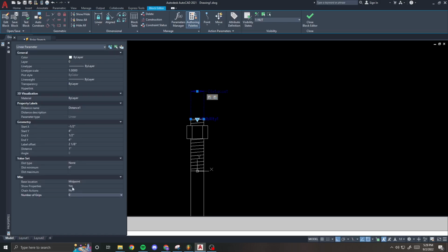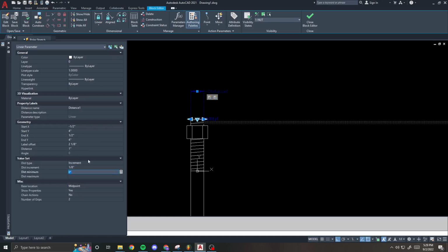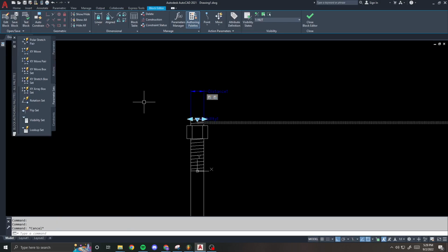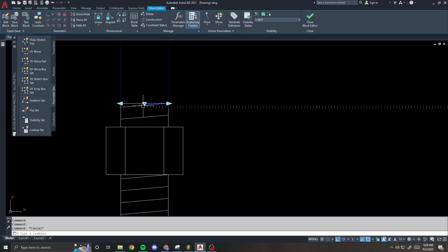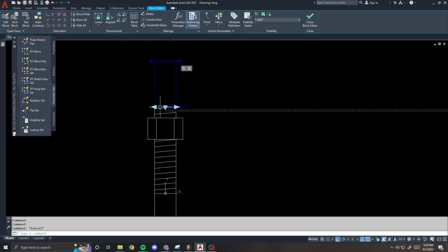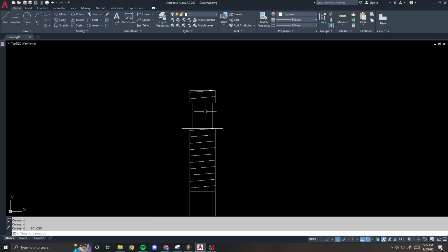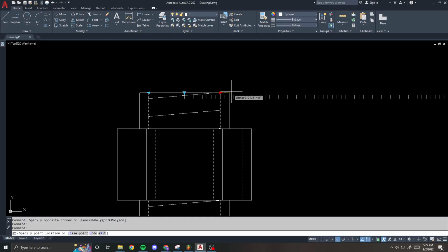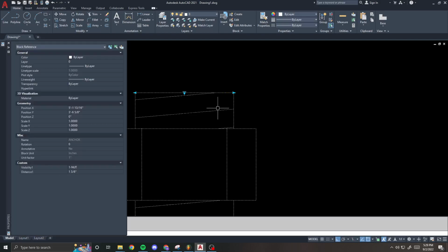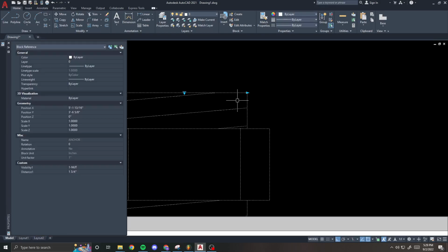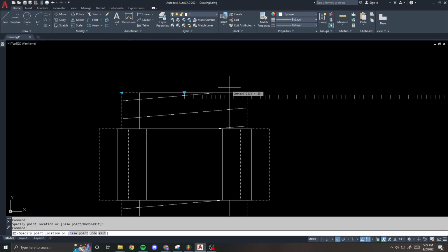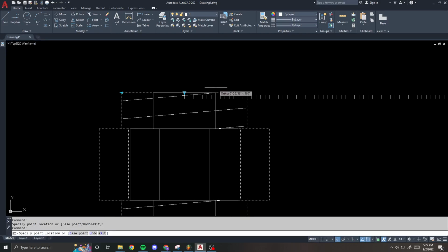And yes, technically, by the way, if you really wanted to use grips, you could set your distance type to increment, and you could set your increment to 1/8, because most of these bolts are working in 1/8. These little hashes let you know that you're working in 1/8 inch increments. So if I close and I save, you'll see it's going to snap, right? And then when it snaps, it's working in 3/8 inch increments. You could do that. But why? Because you don't know exactly what the dimension is, right?